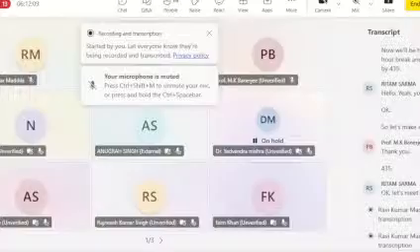So how to do so? We'll select the model, right click on it, and go to the selection information. So here you can see the minimum and maximum sizes in X, Y, Z. It's all shown over here. Basically we need only X and Y. So from there you can directly get the length and set it in the plane. So I'll click the plane, and in the plane we can define maybe 100 by 100.